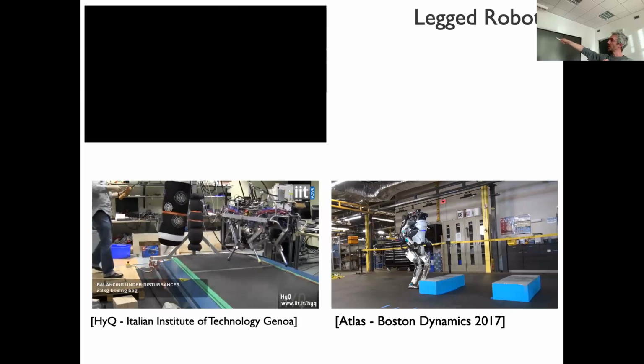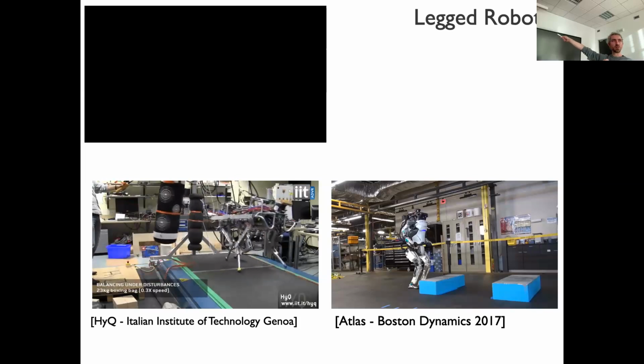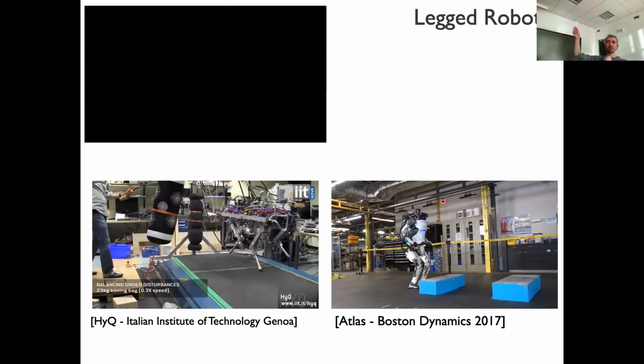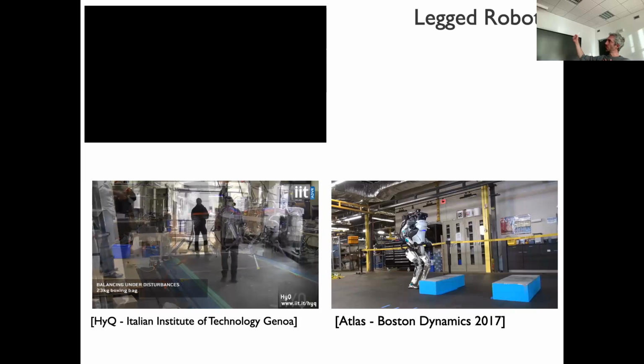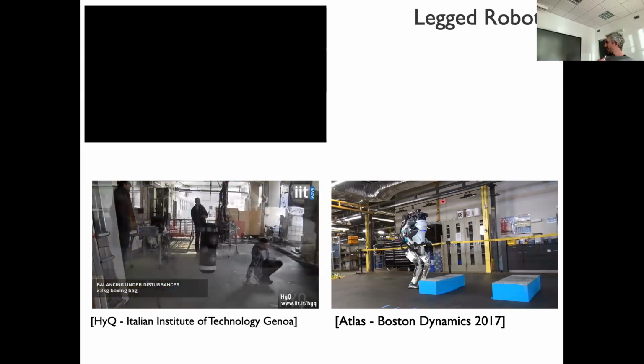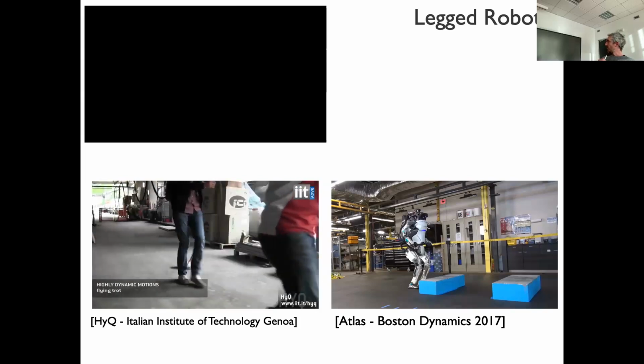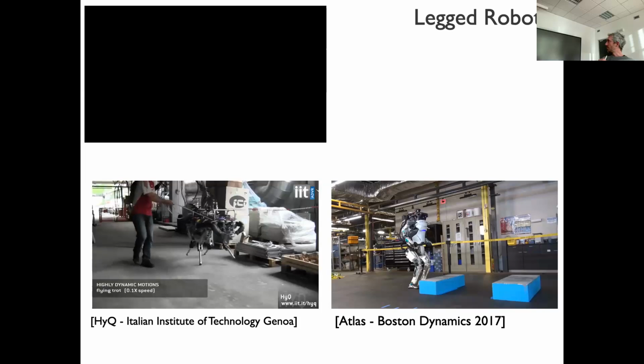I think it's completely hydraulic, or maybe it has 2 out of 3 degrees of freedom of the leg which are hydraulic, and one, the yaw, which is electric, but that's kind of a detail. And hydraulic robots are extremely powerful, so they're very good for doing extremely dynamic movements.